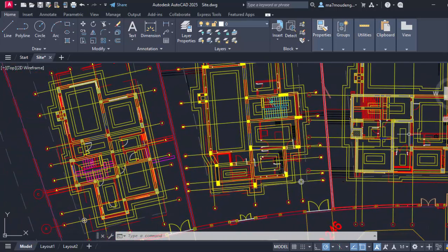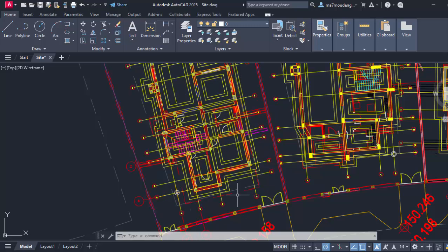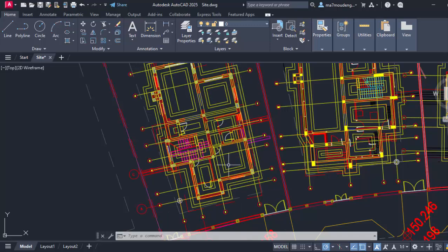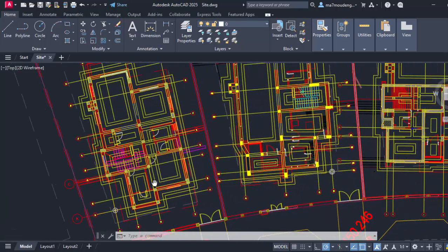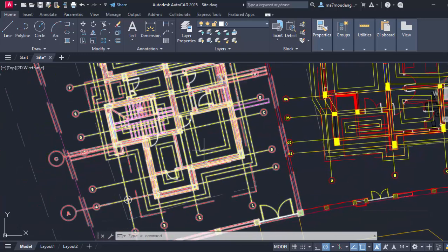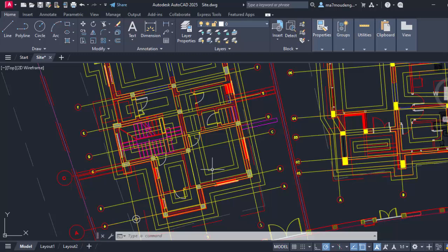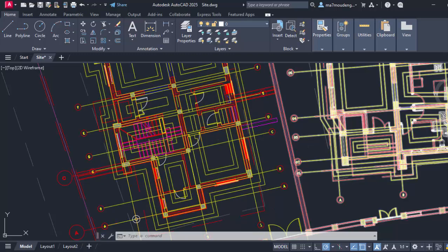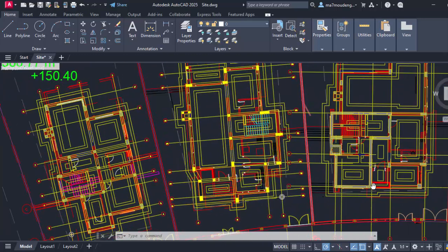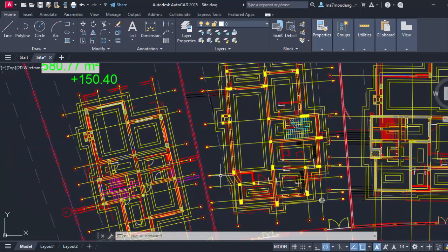The most important thing is, if you have multi-discipline models, or many disciplines working in the same building or same project, but each one of them has a separate Revit file, all of them should have a shared project base point. This cannot be different from discipline to discipline. It should be the same for the same building. This is the most important thing right now. For this building it could be something else, and for that building it could be something else. At the end, it's project related.